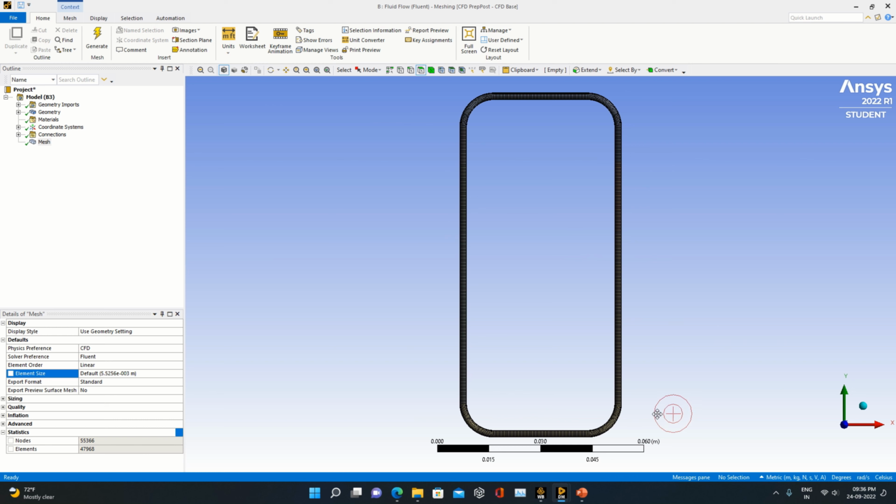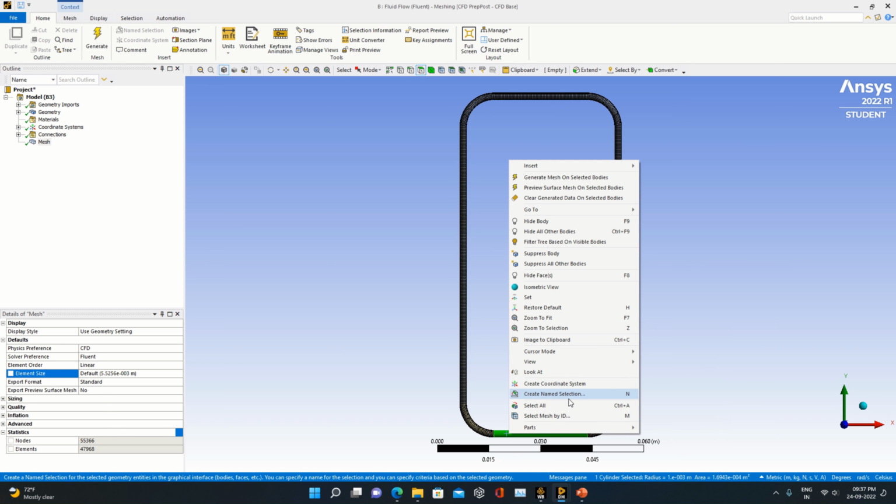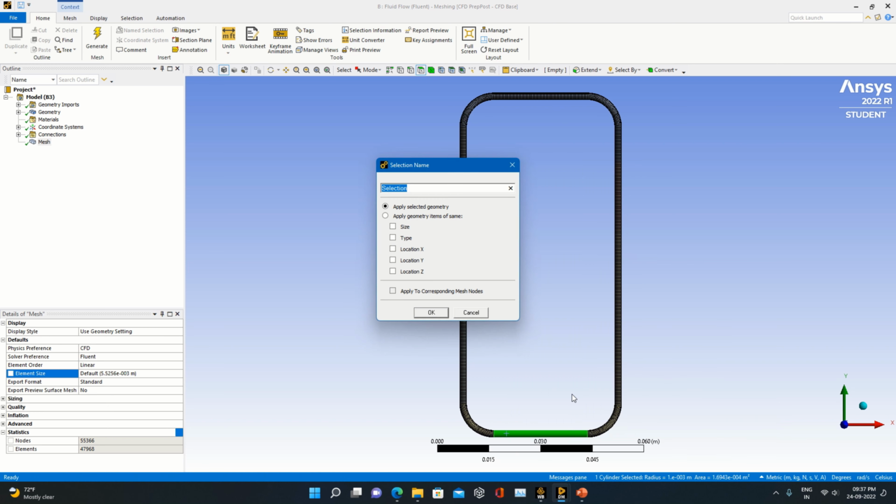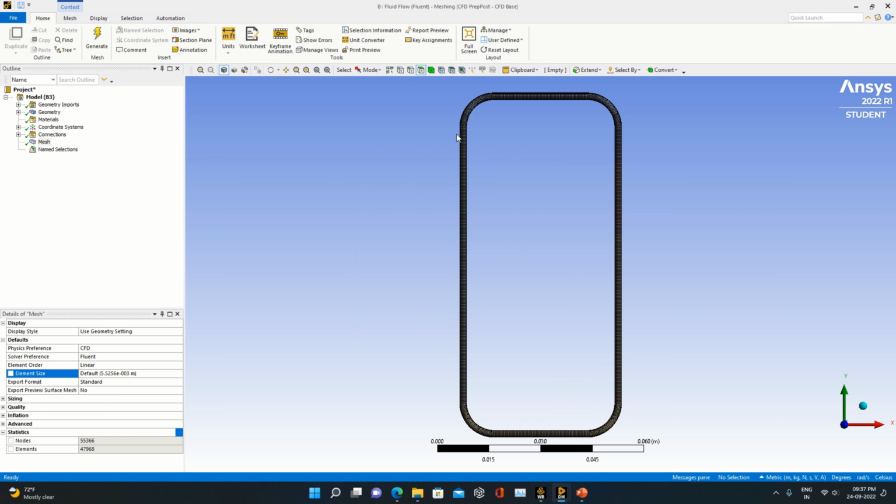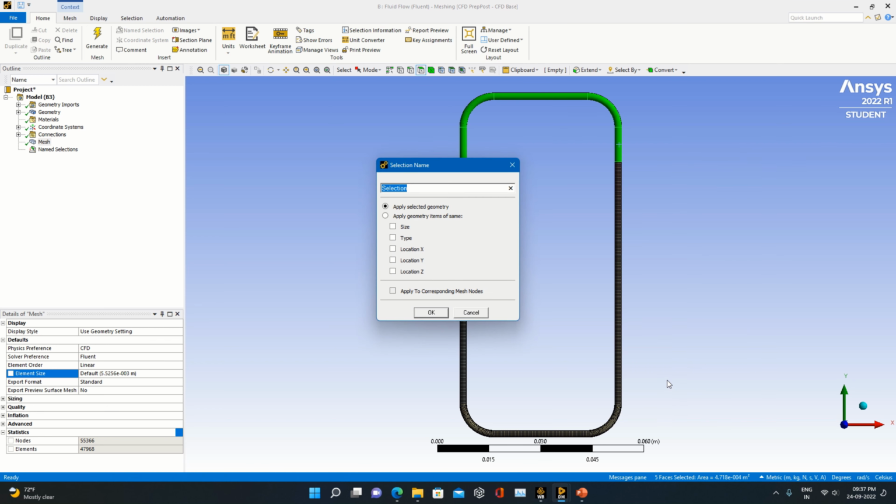So right now just specify whichever we are having as an evaporator. Say for example I have this bottommost portion, I say it's the evaporator. If I say this as the evaporator, how the heat transfer will take place, that we can understand from it. So simply you can select whatever surface you are having. So I will just specify this as a heater over here, and you can specify the remaining portion as a condenser. So select that portion and select it as a condenser.